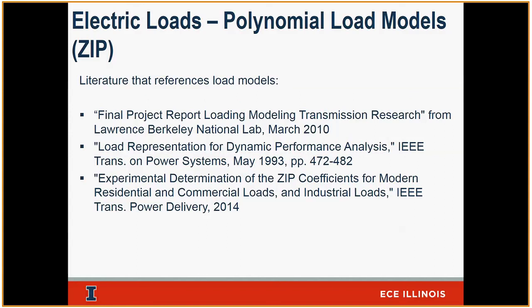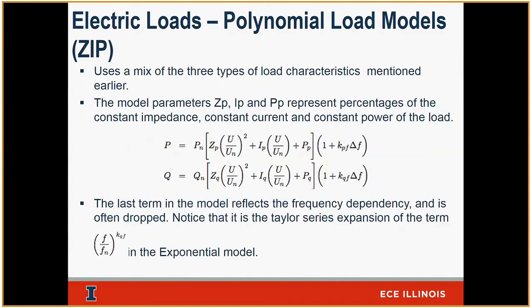So I have a question. Yeah. Do you guys take in these zip models, are there any factors which consider the harmonic effects on the grid? Let's say there's a load which is polluting the voltage and current profile on the grid, and downstream there's a customer which, I know there are IEEE norms which dictate how much pollution you can create on the voltage and current profile. Let's say there's a hospital which needs a proper current and voltage profile. So in these load models, do you guys consider that effect?